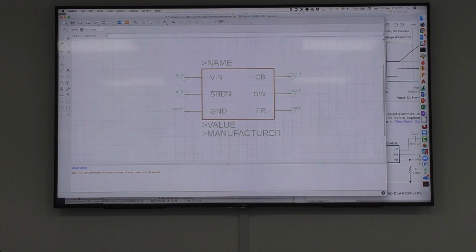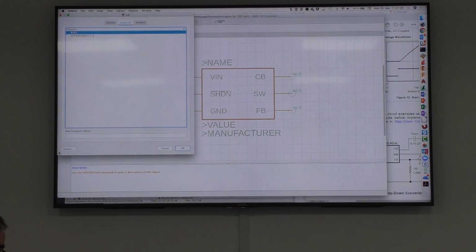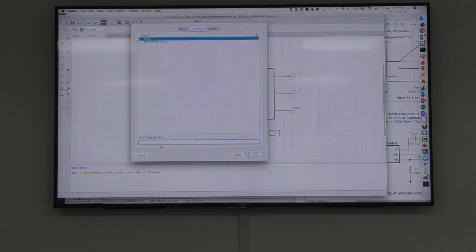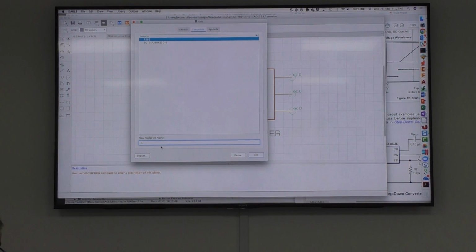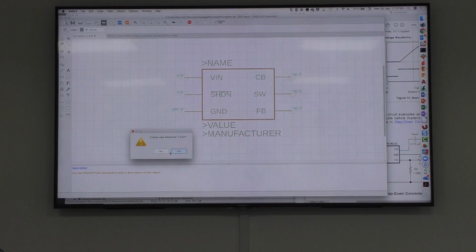Yeah. And so the next step, maybe we should save the files for that one. And then I go into the footprint editor. New footprint, there's the list of what we have already. Yes, here as well, please think of a reasonable name. There are some, the manufacturers say that's the component or the footprint is a QFP 100 or something like this. Then name it this way. I don't do this because, you know, I like crazy things.